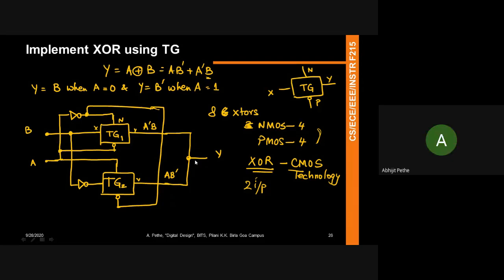Okay. So Sarthak, how did you get 8 transistors? So Sarthak, an inverter requires 1p, 1n. TG1 requires 1p, 1n. So there are 4 components with 2 transistors each. So 8 transistors.